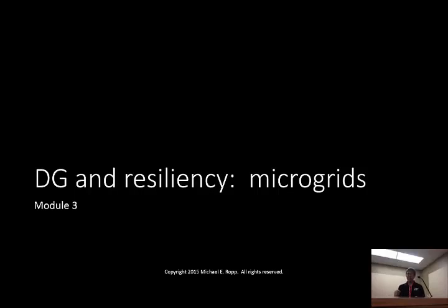The probability of getting that close of a match and keeping it for any period of time is very low. It's less sensitive in real power, so you might be able to be off by 5 or 10% in real power and still not reach the trip threshold that would be triggered by the real power. So I'd say maybe on that order of 5 to 10% in real and less than 1% in reactive.